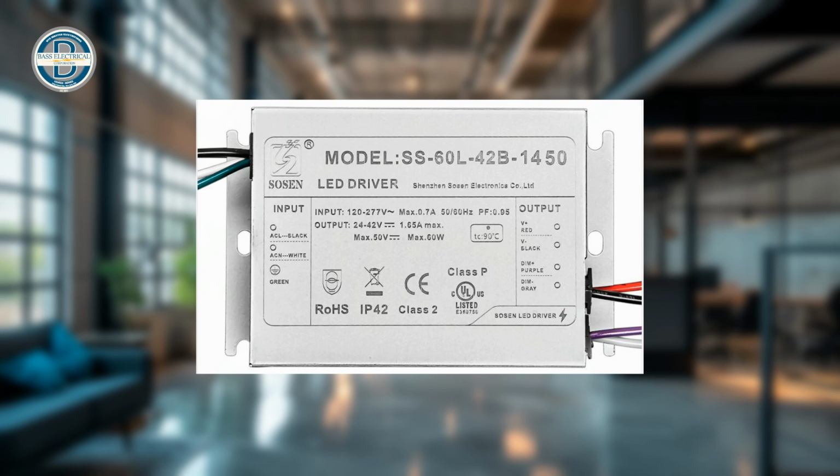On the opposite side, we see the output cables. Red and black carry the 24 volts to the light fixture, and the purple and gray cables connect back to the dimmer to provide 0 to 10 volt dimming control. When wired properly, we can control our intensity for our light fixtures within this system. Now that we understand how to read a driver, let's try a real-world scenario.